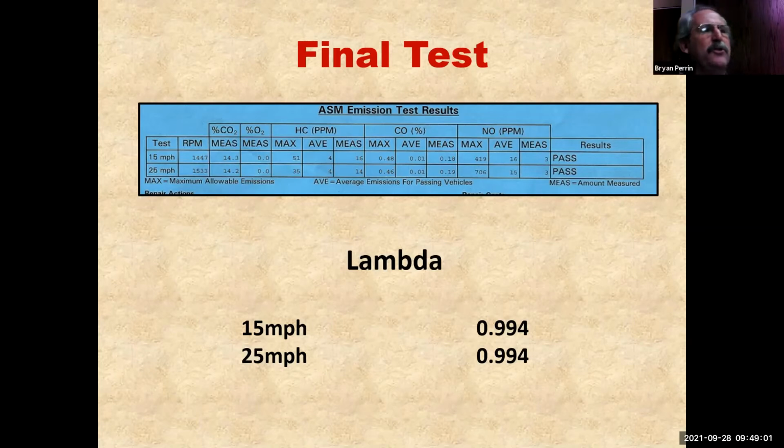So tomorrow I'm going to show you guys something else really cool. I'm going to talk about volumetric efficiency and volumetric efficiency testing, which is a high level test that we use by using a scan tool and a little bit of common sense, and can actually figure out real quickly if something like a mass airflow sensor is bad, or if I have a plugged catalytic converter or things like that. So it's a high level test that gives us a pretty clear direction a lot of the time. Very quickly.